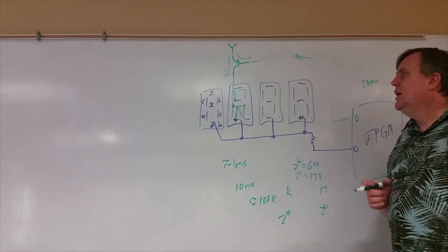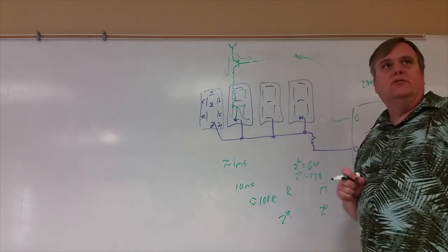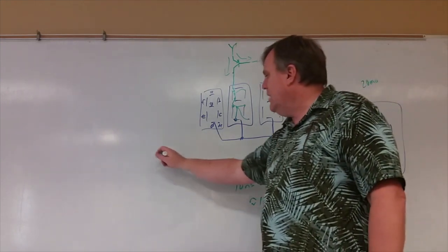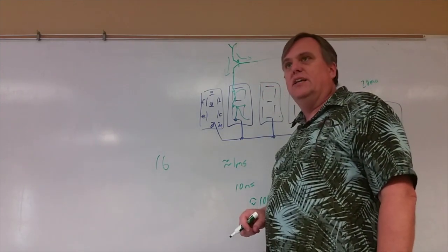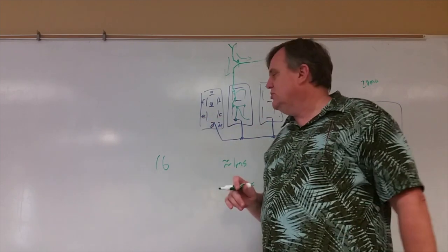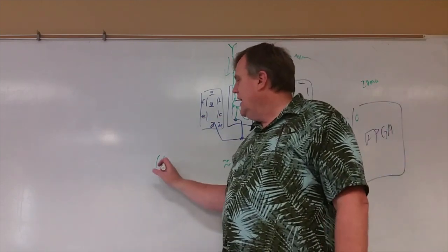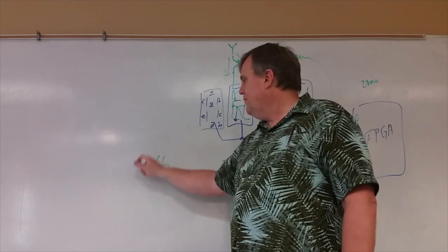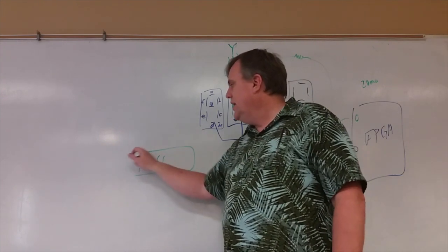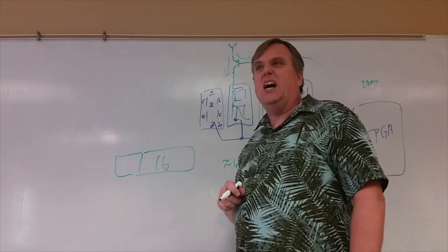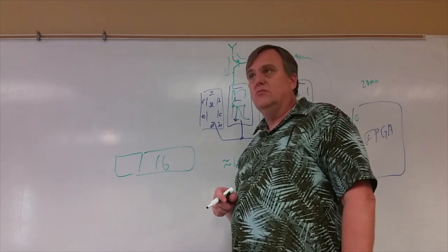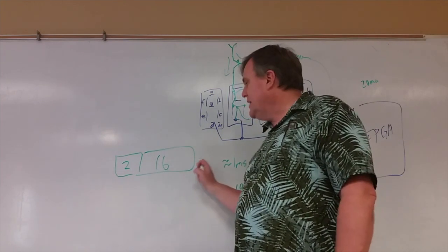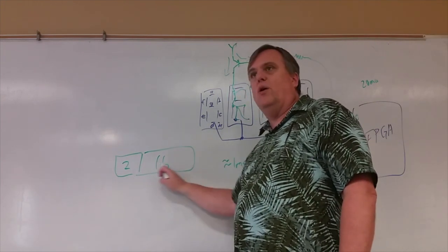How many of these do I have to switch between? 4. So imagine I took that 16-bit counter. That'll get me to around my millisecond zone, and then I want something that's going to switch roughly every millisecond. So if I've got 16-bit numbers here, and I peg 2 more bits on the left, the highest bits, you'll have to count all the way through these 16 bits till they're all 1s.